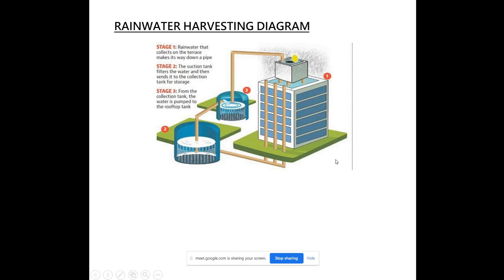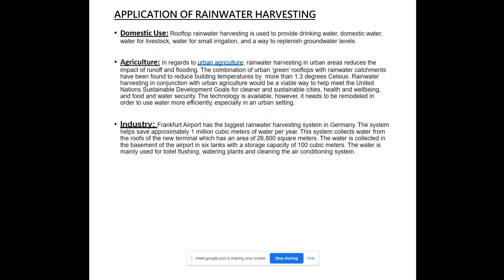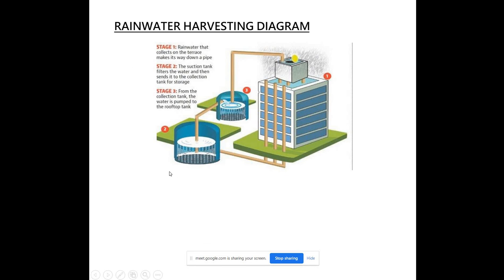Now, the management of water resources. Water management is the activity of planning, developing, distributing, and managing the optimum use of water resources. Canals, tanks, and eries must be desilted regularly during the summer months. Creation of small reservoirs and percolation tanks to hold runoff water must be implemented and maintained well. Harvesting rainwater and storing it in small ponds ensures water supply during summers.